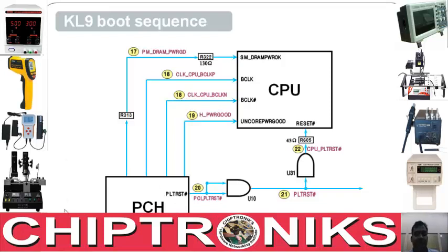And there is a very important question: how does this clock generator inside the PCH operate? Where does it get inputs from? There is a management engine BIOS, ME BIOS, in the SPI BIOS. It's the job of the management engine BIOS to initialize these clock generators. And I'll discuss this ME BIOS inside the SPI BIOS, which is very important.